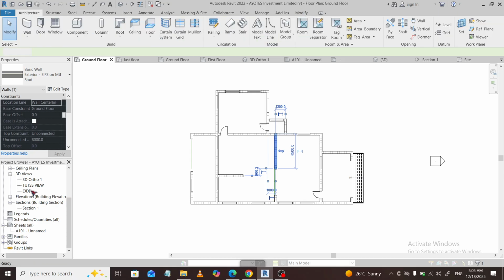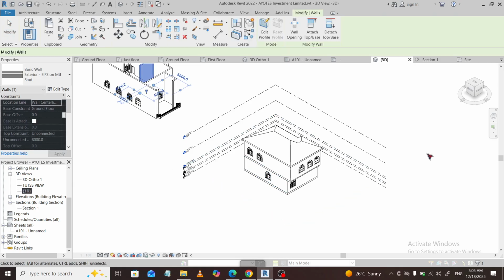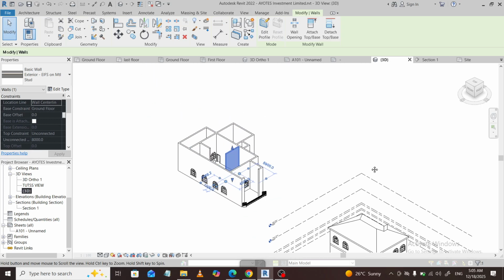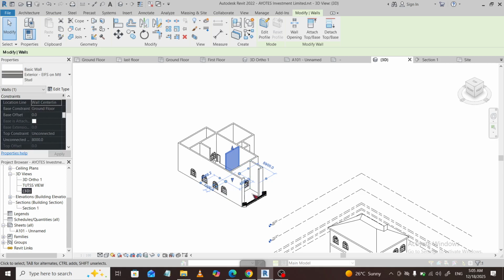When your rectangle looks right, click Finish to complete the sketch. Revit will cut the wall immediately. If the opening doesn't appear as expected, double check that the view's detail level and cut plane allow you to see it. Remember, this is a basic void cut. It doesn't include frames or trim like a door or window family would.